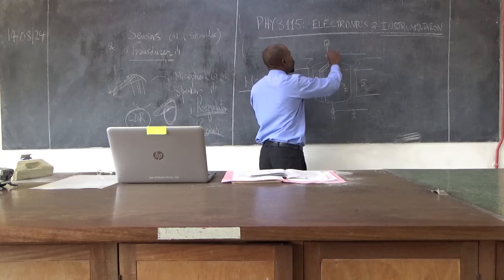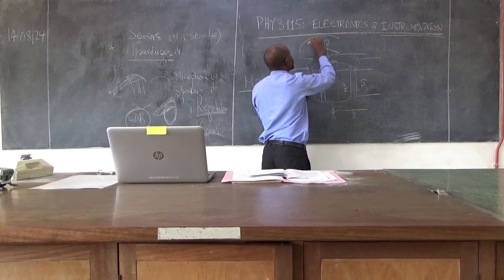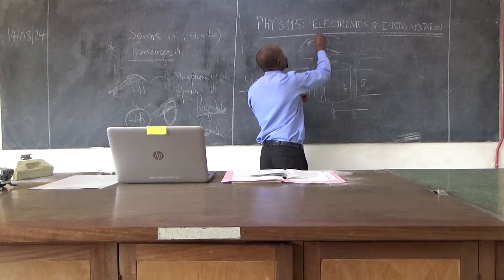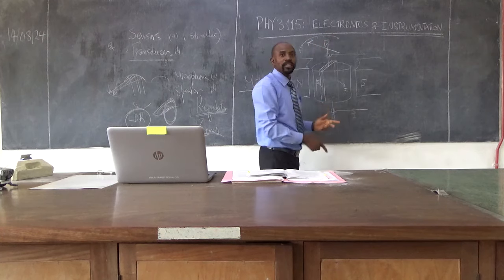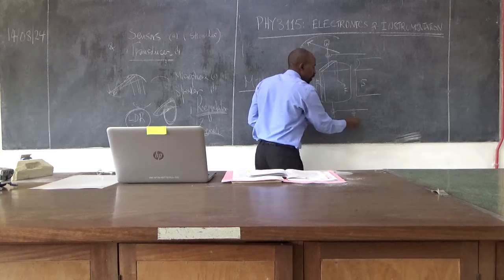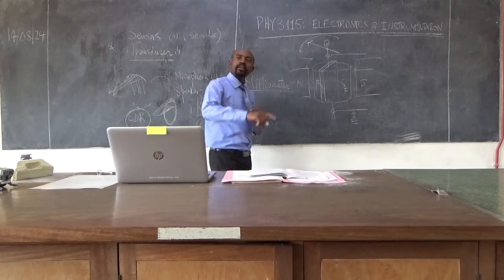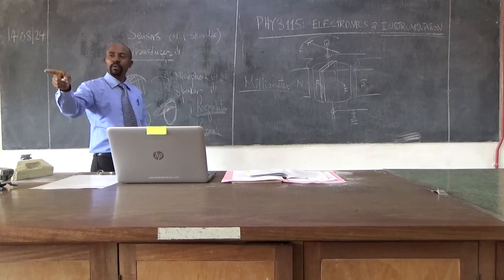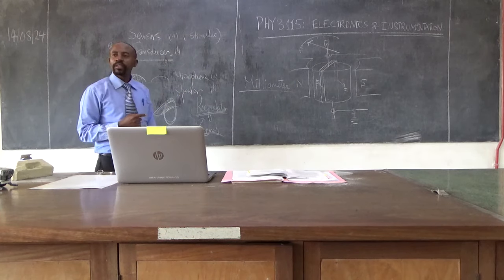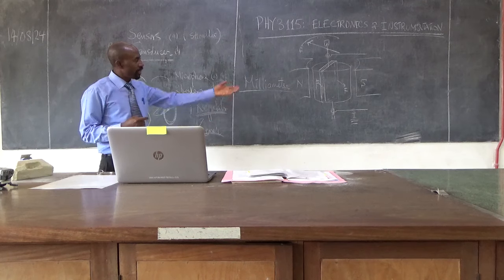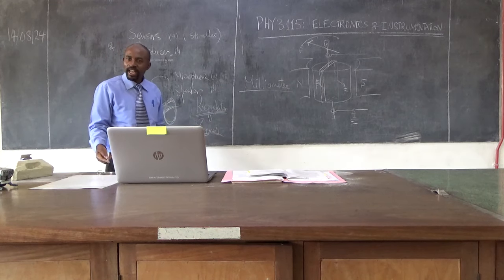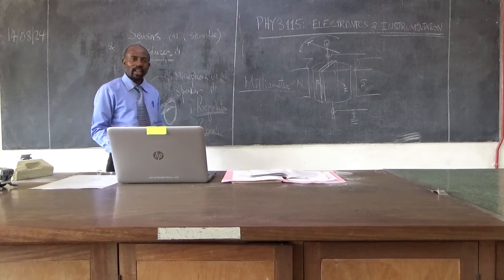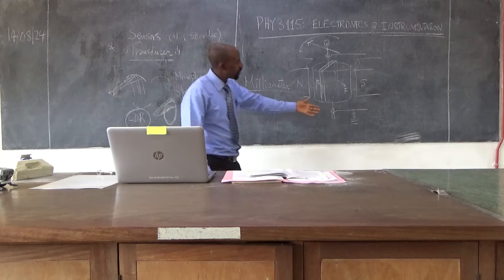A couple, two forces equal but opposite. Then you get this one, the torque. So the twist makes this pointer here to read the scale and then start counting. The magnitude of the current you are bringing in will be related to the magnitude of the response of the pointer to give you the value. So it's a detector, it's a sensor. The current is your stimulus.